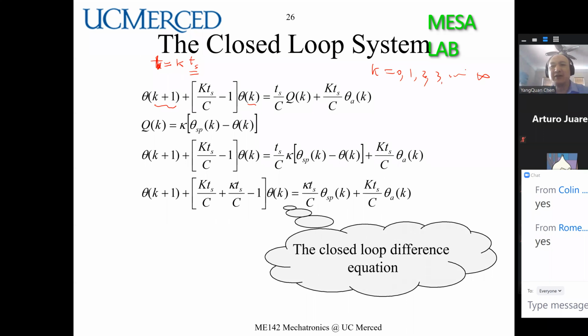So yes, we can write it this way, and now we can write the control at k. This is my u, and this is my error at k. This is proportional control, and I put it in here. Then I get something like this: θ(k+1), and you also have θ(k) here. Move everything to this side and you get this term.